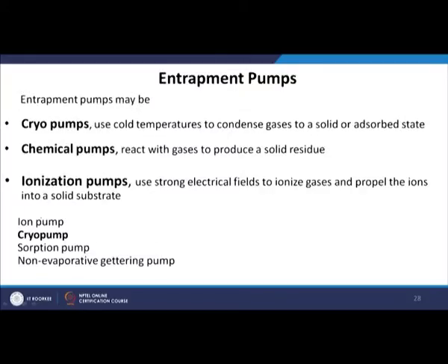And finally, the entrapment pumps, they absorb the gas molecules or ions. They can be cryopumps, which use cold temperatures to condense gases to a solid or adsorbed state. Chemical pumps react with gases to produce a solid residue. Ionization pumps use a strong electrical field to ionize gases and propel the ions into a solid substrate.